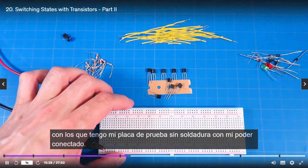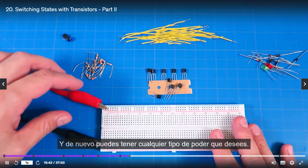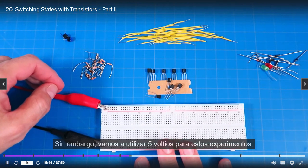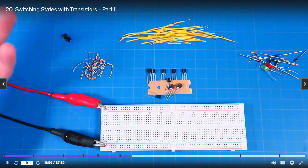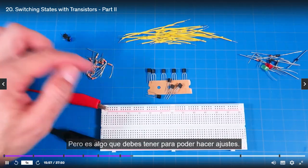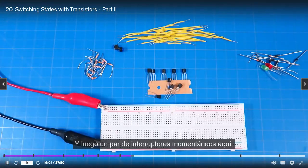I've got my solderless breadboard with my power hooked up to it, and you could have any kind of power you want. We're going to be using 5 volts for these experiments though. Having a bench power supply would be really useful. If not, then you're going to have to use a regulated DC supply or something, but you need to be able to make adjustments. And then a couple of little momentary switches here.